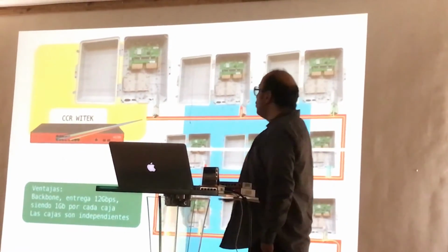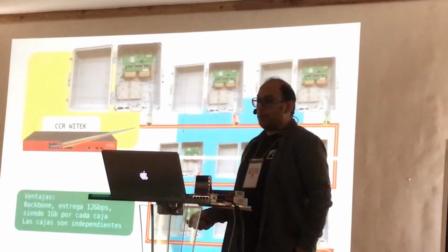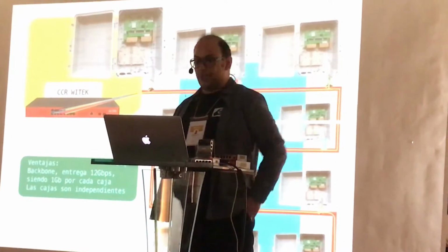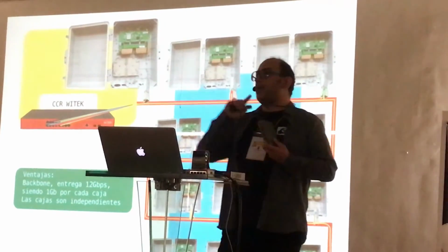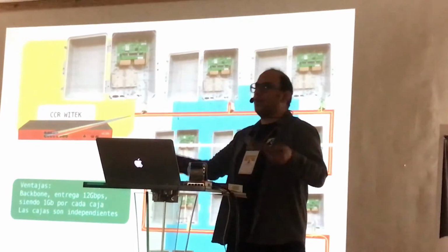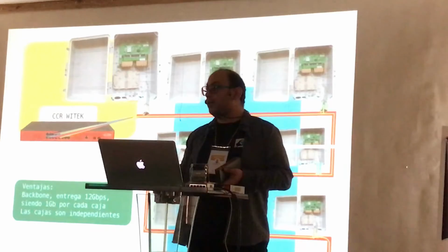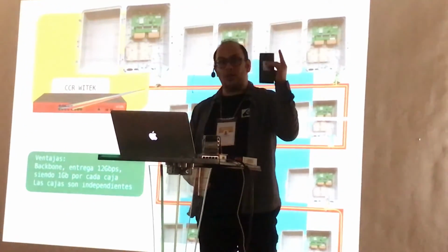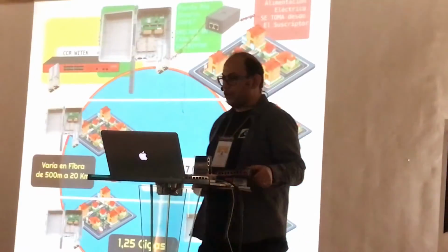To expand in an outdoor environment, you may use fiber or you may use Ethernet. You still can expand it. For example, one of the products is 200 meters. This is what we call long range. It means you can have your switch here and run an Ethernet cable 200 meters. At 200 meters, you can power up a camera or access point or whatever. As you may know, Ethernet cable doesn't work over 100 meters, so this one boosts the power to be able to power up your device.